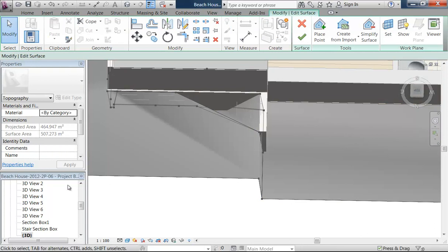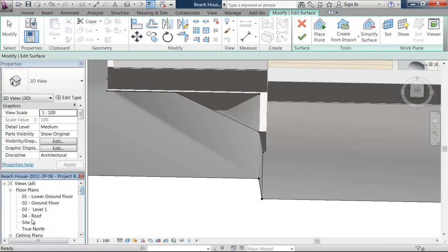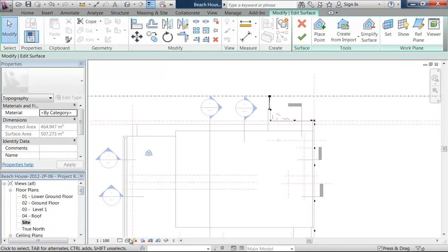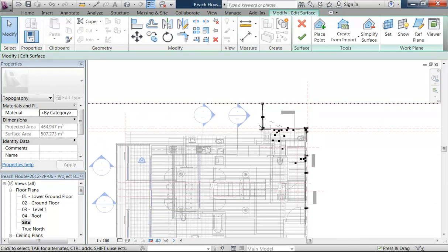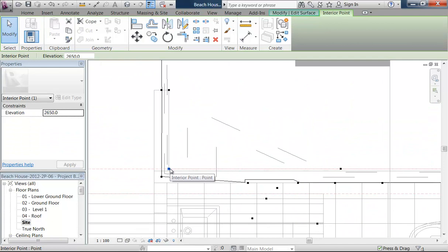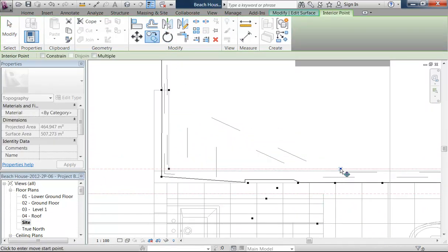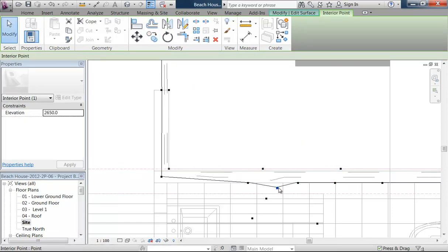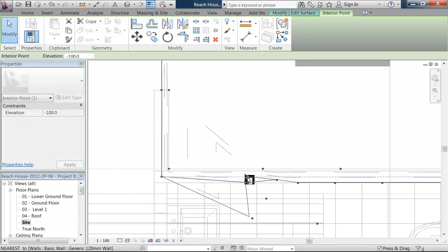Edit surface, back to the site plan, in wireframe. So I've got these points here that are 2650, and you can actually copy those along rather than making new points. You can see there that it's going a little bit into the building, the ground, so I'm going to bring that back just by moving those points rather than...